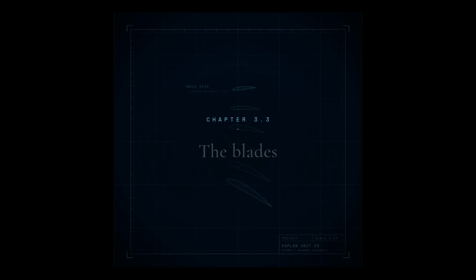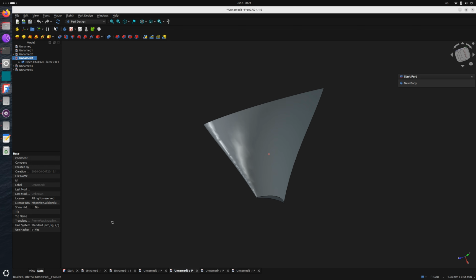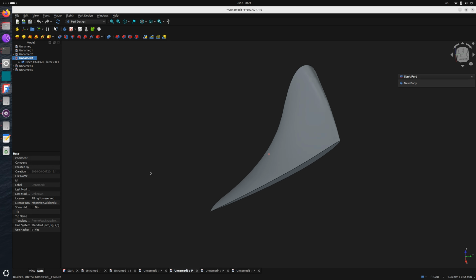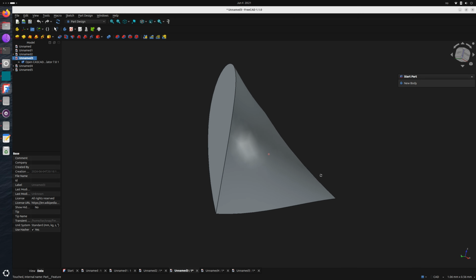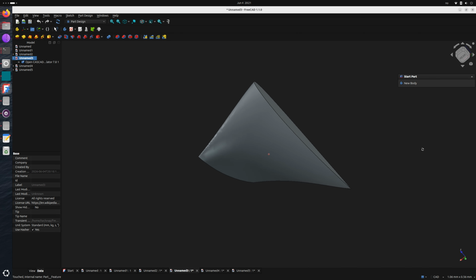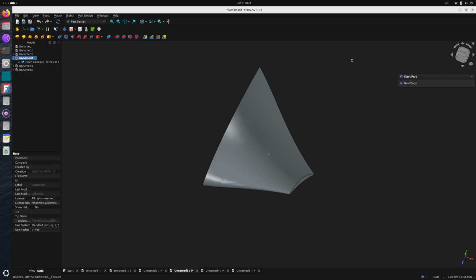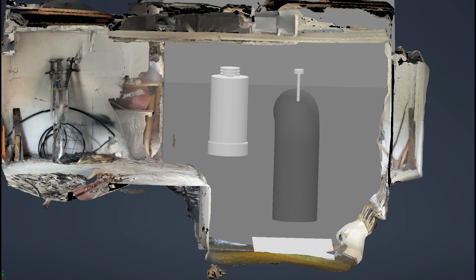On the suction side, they make lift, and at its lowest point, the blade suction side, in the flow past the hub, the local pressure dips towards the vapor pressure of the water. If we cross that line, it will flash boil and lead to cavitation eating the metal. So I size the hub so that the low point lands just above the vapor pressure.